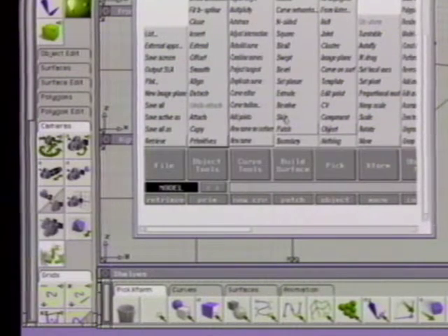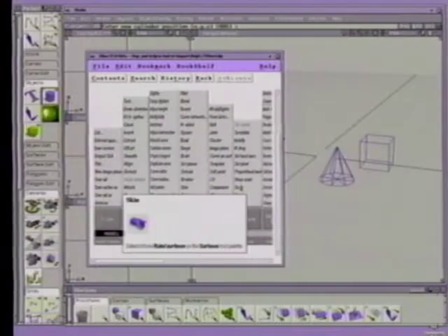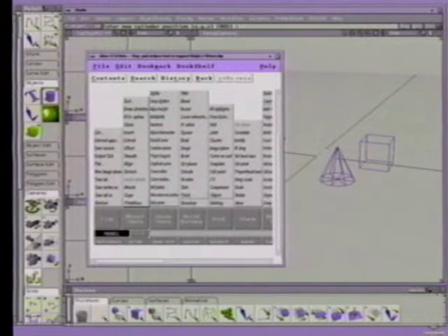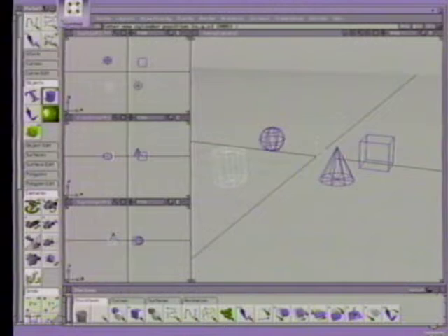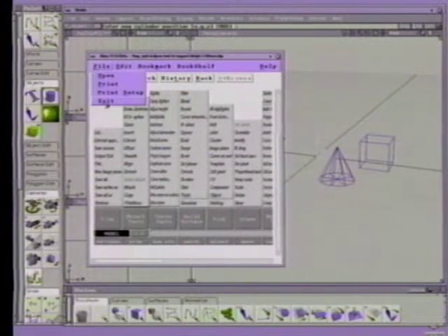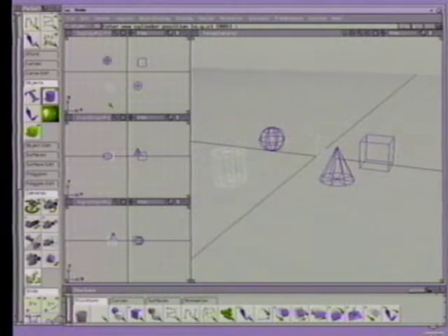Next, click on the Skin menu function from the Build Surface menu. This time you find that the tool is in the Ruled Surfaces subsection of the Surfaces section of the tool palette. If you want to keep this window around to learn tool locations, you can minimize it for easy access. For now, let's close it. With this online assistance, the locations of all the version 6 tools are at your fingertips.